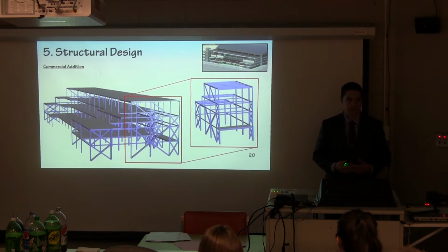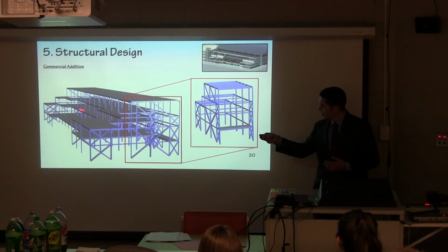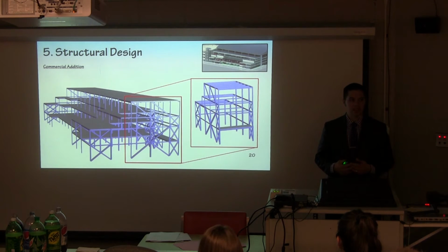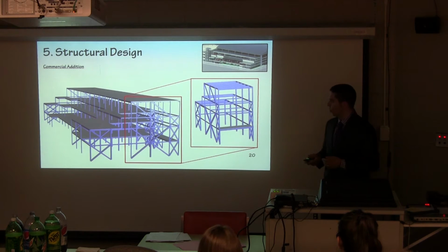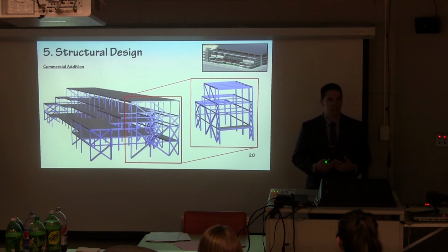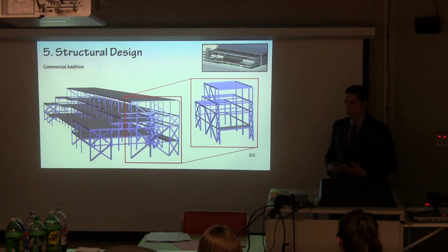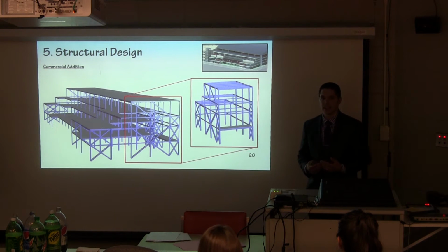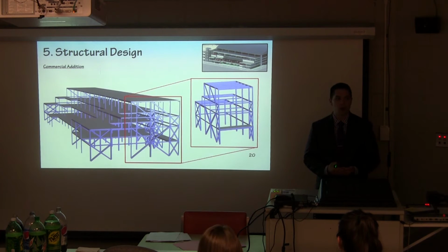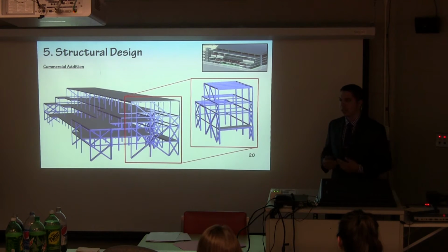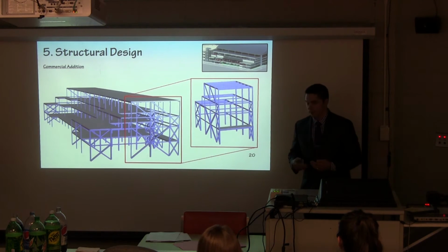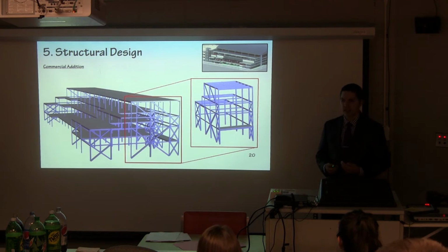There are 3 terraces, and the bottom and the next floor up have a 10-foot cantilever system, an overhang. On the third story, that actually had a 20-foot cantilever system, and it's only a 40-foot beam, so the deflection was controlling there. In order to fix that, we decided to take the columns below and run them all the way up and through, and Andy was going to give them an aesthetically pleasing view.